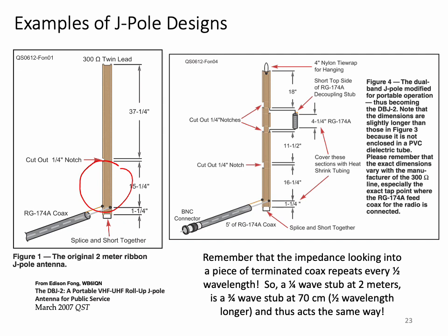Unfortunately, while the impedance match will be reasonably good, the antenna pattern on the third harmonic will not be, resulting in the radiating lobes aiming upwards and downwards instead of toward the horizon as with the fundamental frequency. This makes the single band J-pole operating on the third harmonic a very poor antenna, as it has significant null along the horizon, which is where we want to be pointing. And please take a look at Dr. Edison's articles for much more detail.